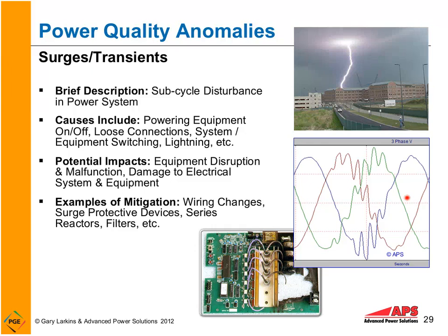to make sure that we have protection against damaging transients. And when it comes to drives, we need to look at also, and power factor correction capacitors, we need to look at the appropriate mitigating factors, whether it be DC bus chokes or in many cases, line reactors or tuned filters on the front of the drive to help protect those drives from tripping. So surge protection and proper wiring are essential for this.